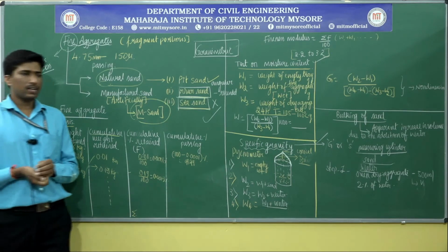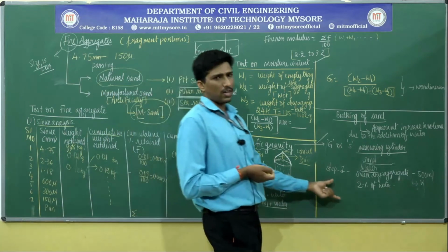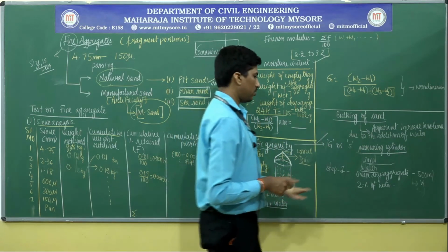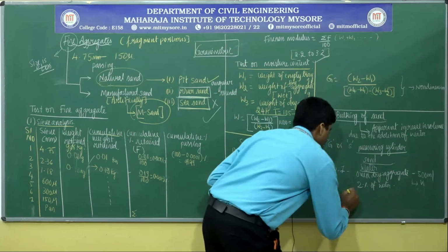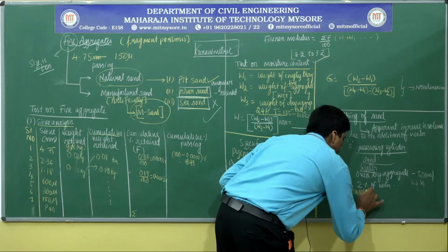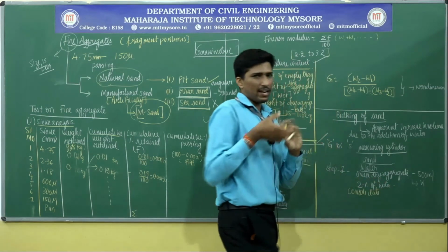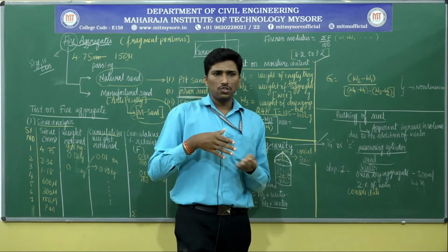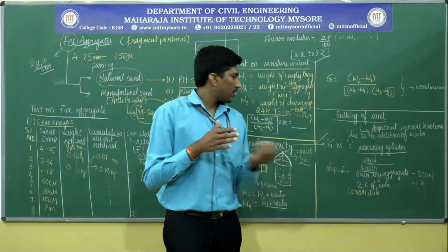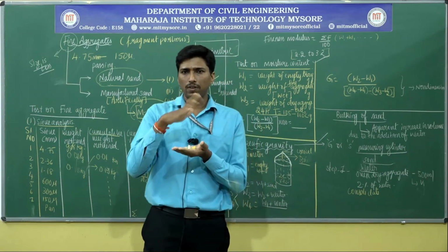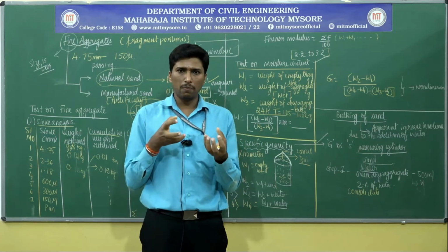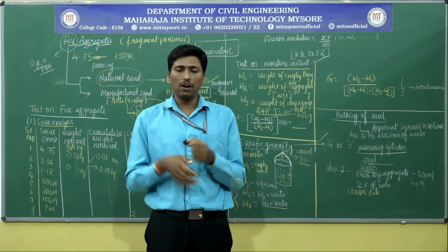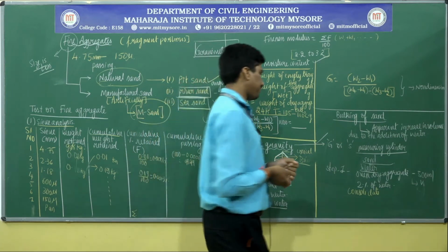Finally, consolidate it by shaking it. You need to consolidate by shaking it, and measure in terms of ml whatever volume you get. Consolidate, because the grains may be loosely arranged. In order to make them properly arranged, you need to shake it, and you will have some sort of consolidation. Things which were not properly or randomly arranged will become slightly more uniformly or homogeneously arranged.